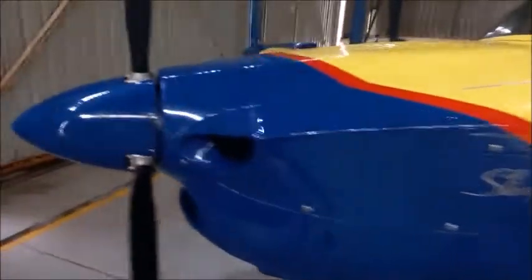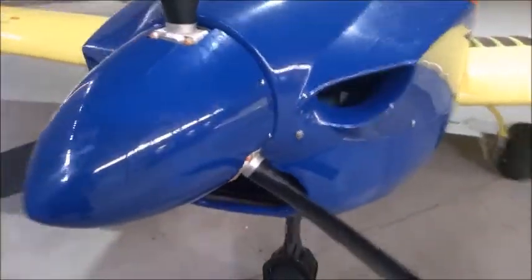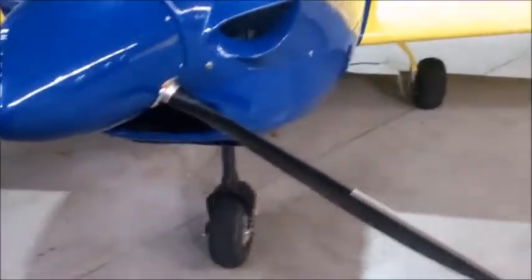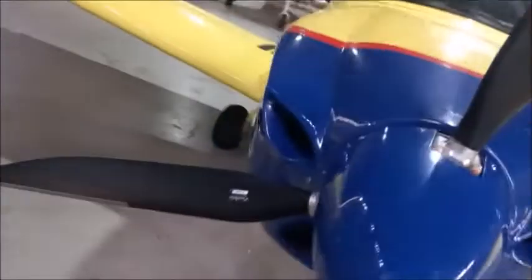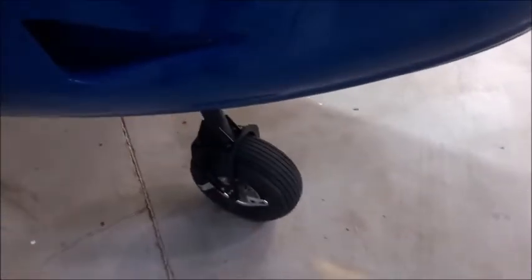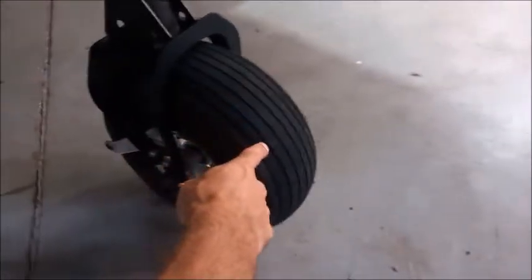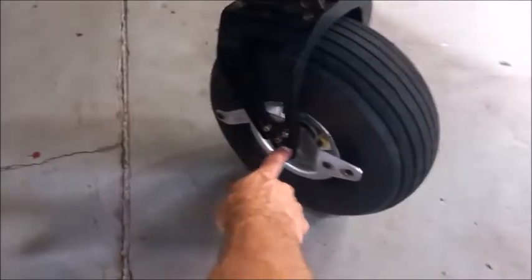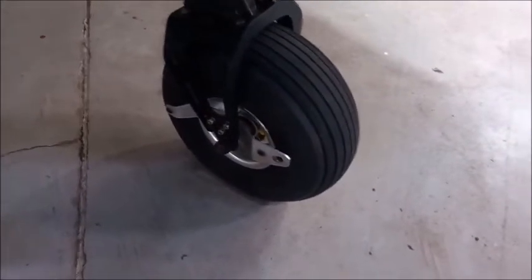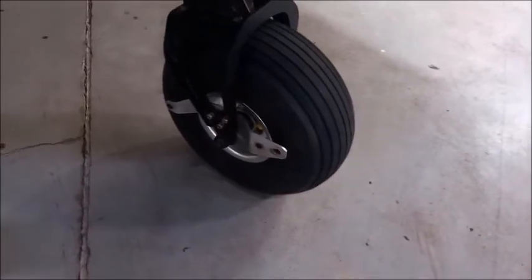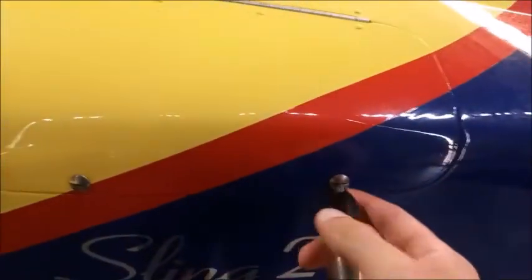We then move across, and we're going to be looking at the propellers, which are what let the airflow pull the aircraft. So we need to make sure all the blades are looking good, inspect them. It appears to be all in order. We then come across and have a look at the front wheel. Make sure that it's straight, and that all the bolts and nuts are in place. We don't want to have a situation where we're busy taking off and the wheel falls off. We then come up to the other side of the engine compartment.